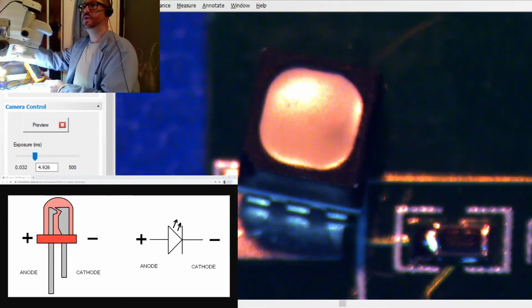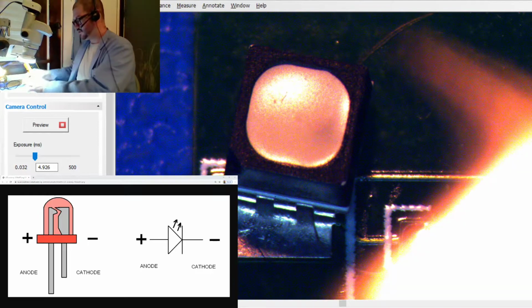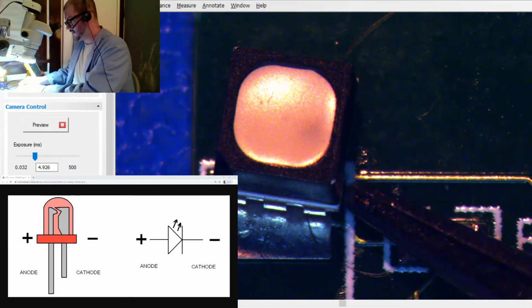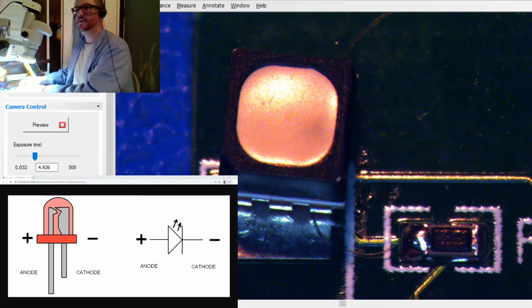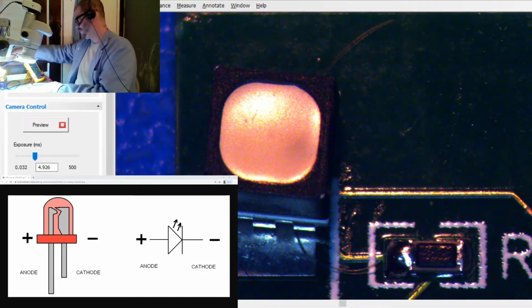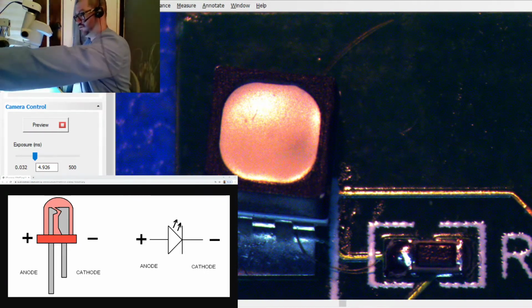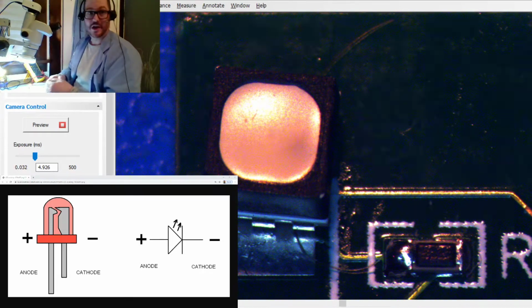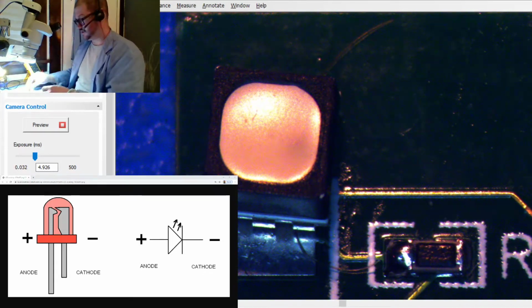So what I'm going to do is take some solder, and I'm going to solder all 3 of the cathodes together, just making it a little bit easier for me to attach a probe down to just one spot, and also to help mechanically fix it into place.